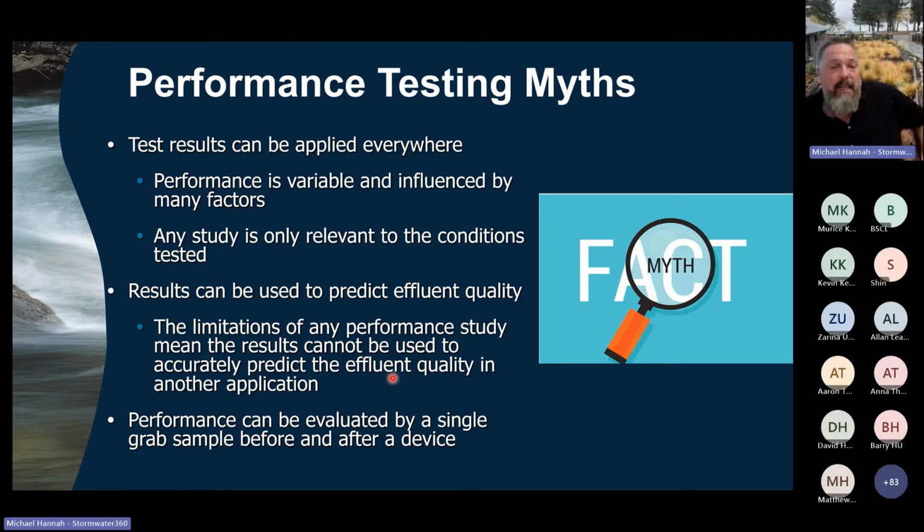And that you can actually assess the performance of any device from simply taking one sample before and one sample after. I highlighted that before because it varies so much. You really need to look at how you collect the load for every storm over a period of time to understand if the treatment device or BMP is achieving your objective.